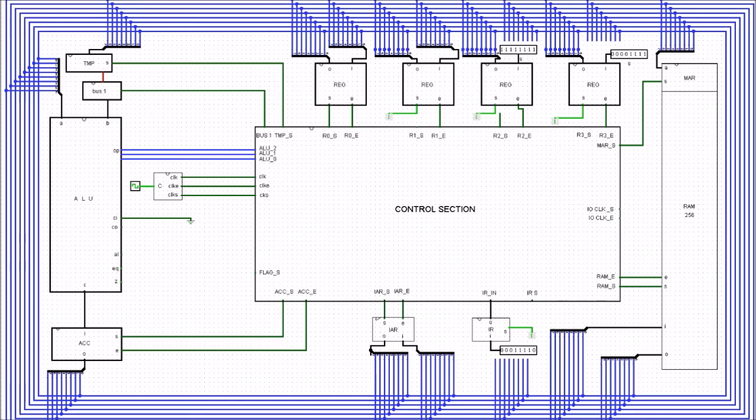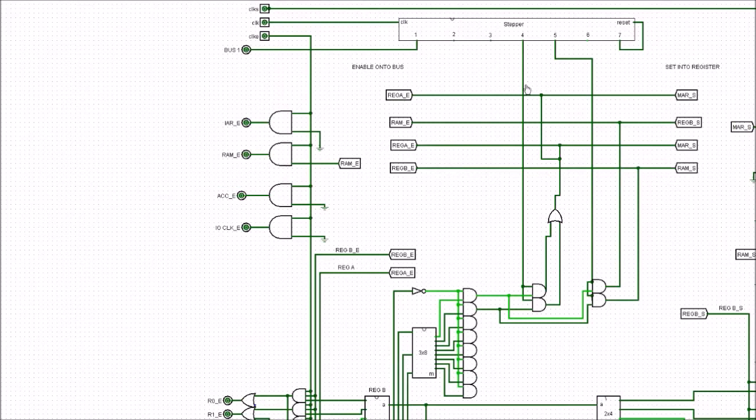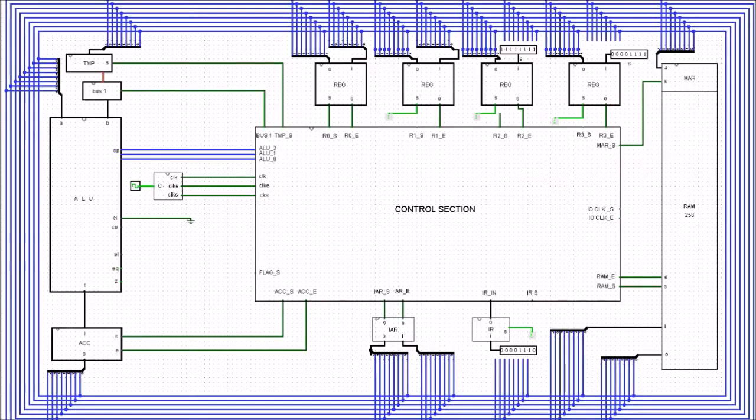In order to do that, we have to set up our instruction address, instruction code here. The instruction code for our load is going to be all zeros, so we can put in all zeros. Now we can check where we are. We're at some point along here, so let's continue along until bus 1 goes high, and we know we're back at the beginning. That's bus 1 going high. So let's put in our 12 clock pulses. That's our 12 clock pulses here.